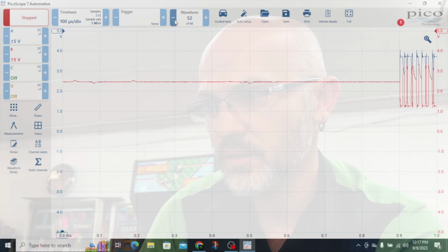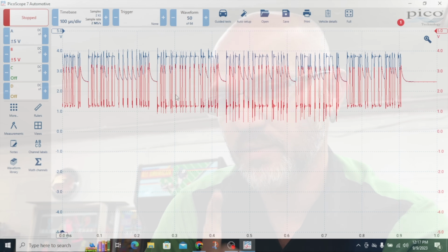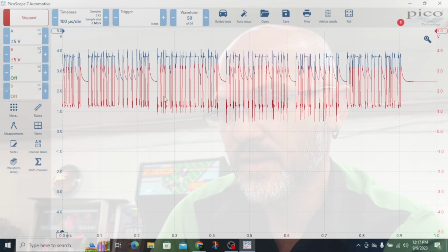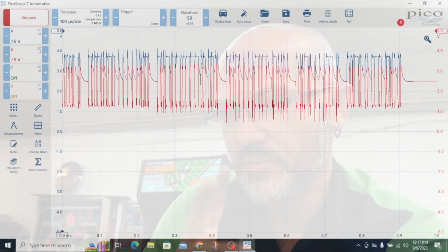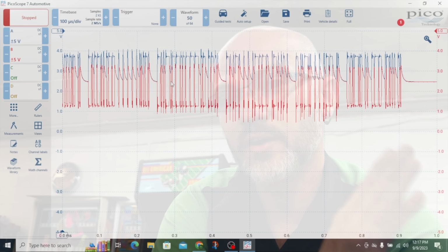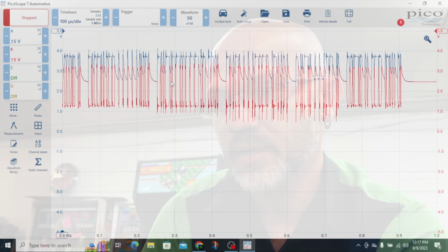And let's see, right there, that looks like the ABS module talking. This is the ABS module talking. I'm almost certain this right here is the ABS module talking. It's because we got CAN high and CAN low. And the reason why the middle here is all kind of wonky looking, the bias voltage getting off, is quite possibly due to the circuit not having enough resistance in it, like the other end of the terminating resistor is bad or broken, something like that.